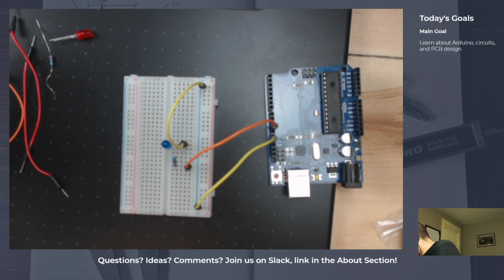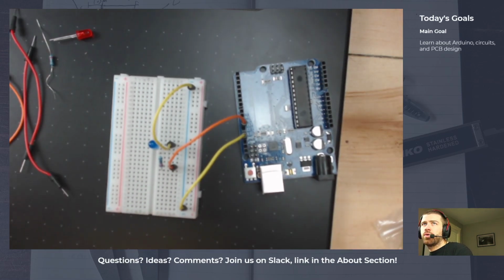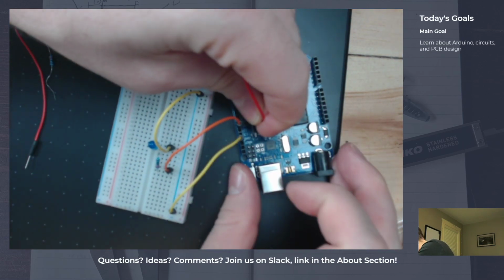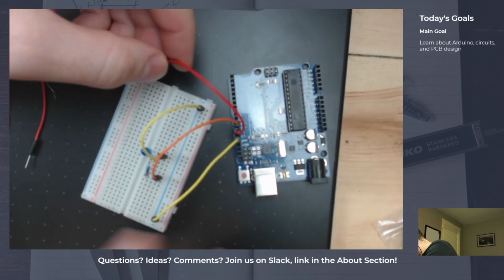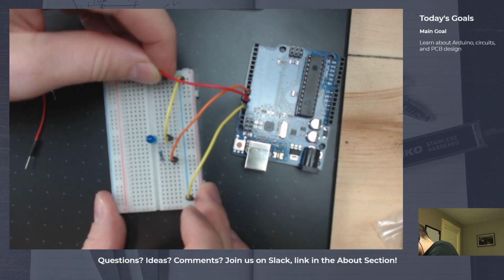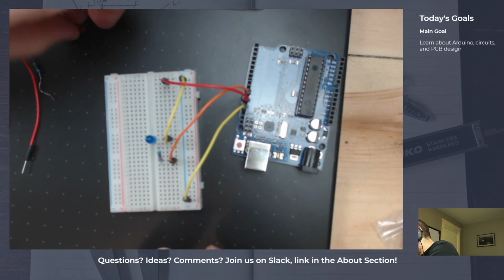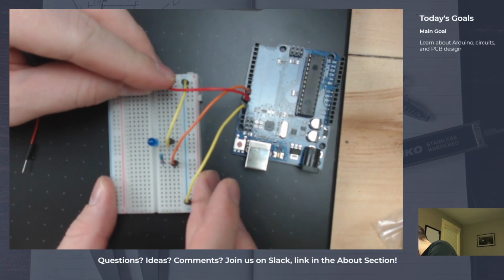So this LED is wired up to pin 11. And in our code, we had wired up another LED to pin 12. So we'll do that. We'll drop a wire in here to pin 12. We'll grab another spot on the breadboard. Doesn't really matter where you do your things in the breadboard. I'll drop it in there. As we talked about earlier, it doesn't actually matter which goes first, the LED or the resistor. You want them together